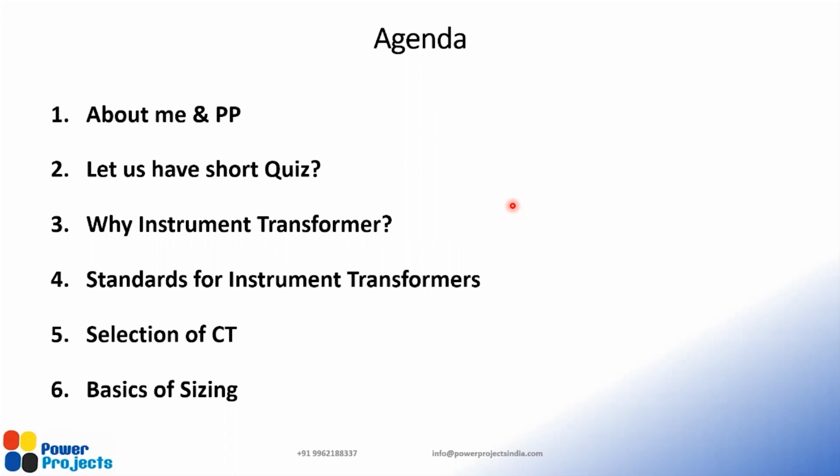If you want to measure 400 kV, you need to insulate that measuring equipment to 400 kV. Even if that may be technically possible, commercially it's definitely not viable. So we need a device which converts this 400 kV to a small value so that a measuring device can measure it. If the predefined scale down ratio is known, then by measuring the small value and multiplying by this ratio, you will be able to know the real value, right?